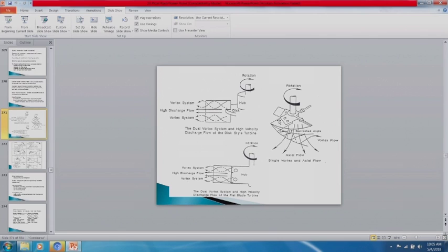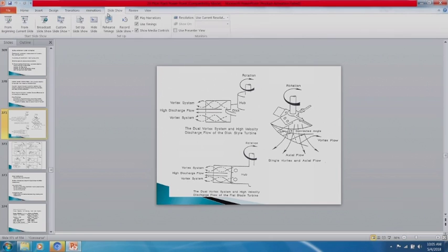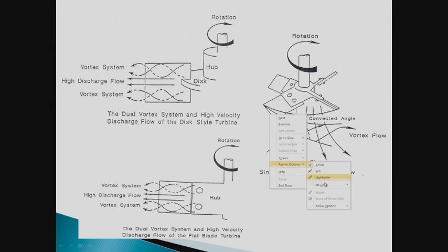By the way, talking about shear zones, the impeller blade has the highest shear zone. If you're on a surface, the surface creates the high shear zone, right? So the high shear zone sits on the surface, and the shear rates can be quite high.